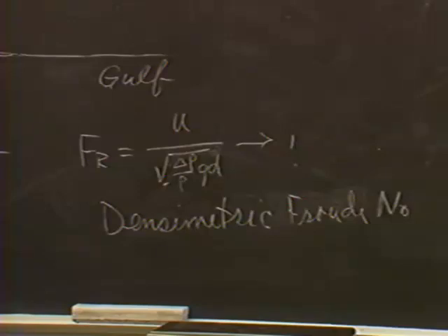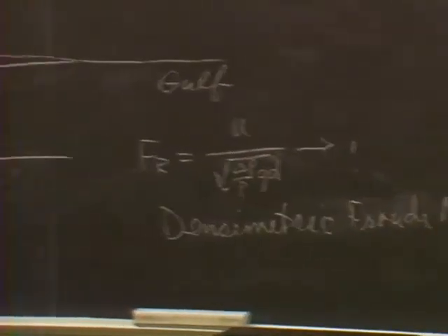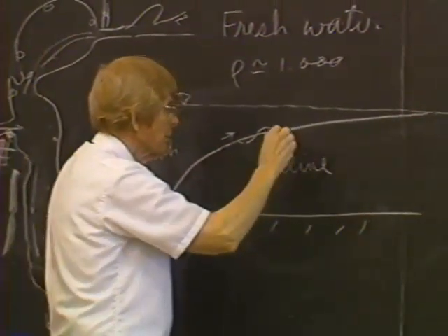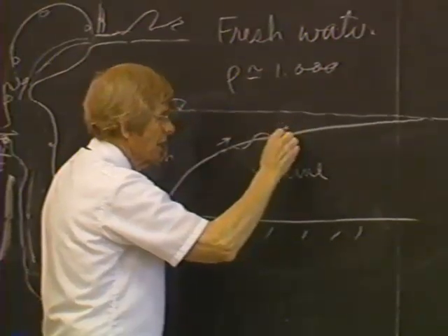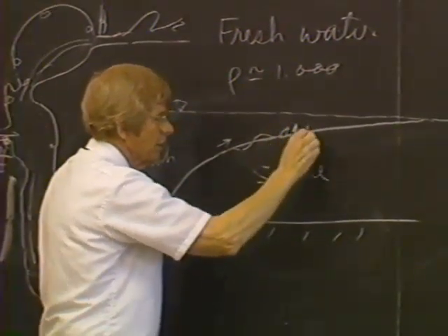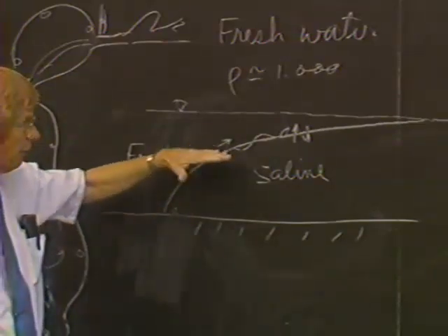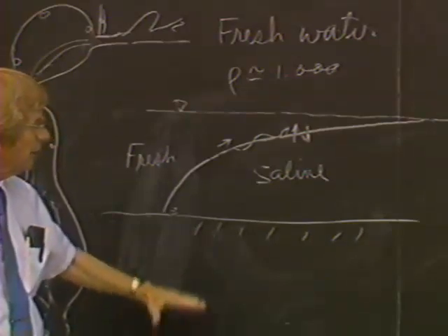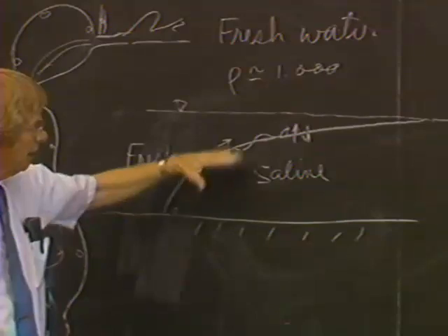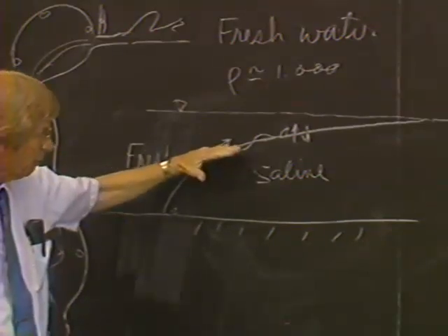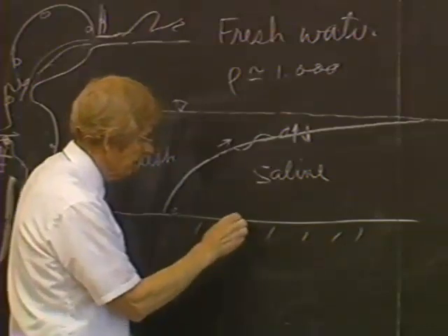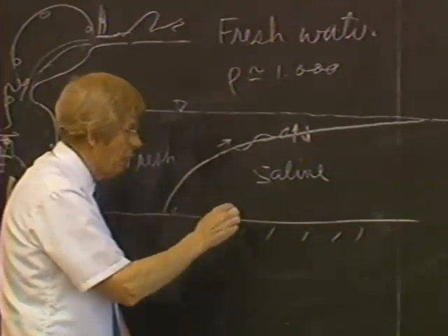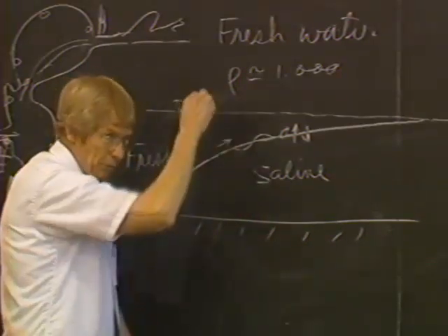approaches 1, then waves form on the surface, and they're reinforced as they go along. That is, the current continually reinforces them, with the result that they break, and there's mixing across that interface. So even when we have a very small tide range, so there's not much back and forth motion, we do get mixing under that particular condition. The reason the back and forth motion causes mixing is because the roughness of the bed and the banks, that is the roughness of the boundary, generates mixing that mixes up through the system.